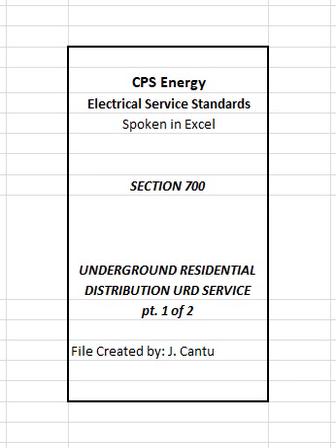701.1 Final grades provided by customer. Customer is responsible for providing finished grades before CPS Energy installs transformers and trenches for primary voltage ducts and secondary laterals. In cases where the final grades are changed after CPS Energy has begun the installation of the infrastructure, the redesign and construction charges associated with the changes will be the customer's responsibility. Customer shall identify all property lines as required by CPS Energy.